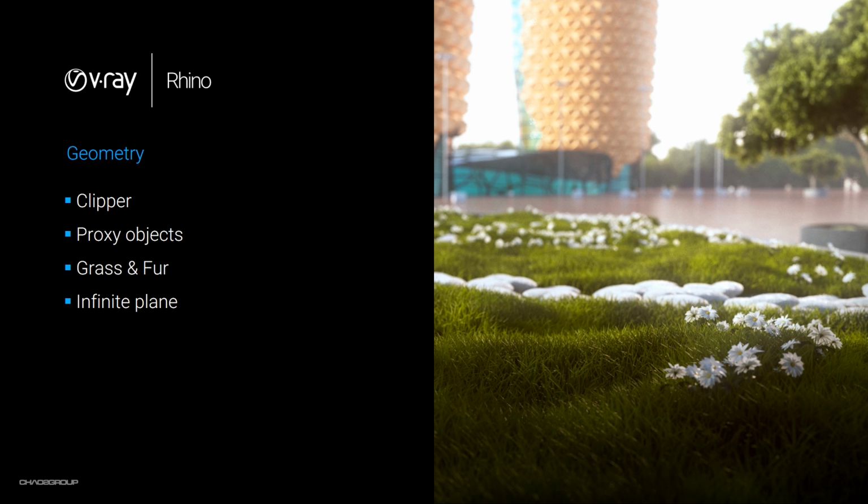This you can find in the tools folder located in the root folder of VRay for Rhino. VRay proxy is another type of dynamic geometry. Again, this type of geometry doesn't exist exactly in the scene. You can see a rough representation of it, but the geometry itself will be built and appear only in render time. Using this functionality will help you in cases when you have to manage a heavy geometry in your scene: grass, cars, trees or any vegetation, high poly geometry of all types.